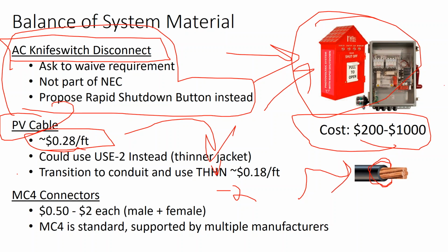But just remember that this PV cable is designed to go outside of conduit, and it has a thicker jacket. So what happens when you put it inside of conduit? Well, you get less airflow in that conduit, so it's going to retain more heat. And with your thicker jacket insulation as well, there's more mass inside of that conduit than airflow. So I just think it's better to use THWN inside of conduit because of heat. It's just a finer point. I mean, it's not a mandate.